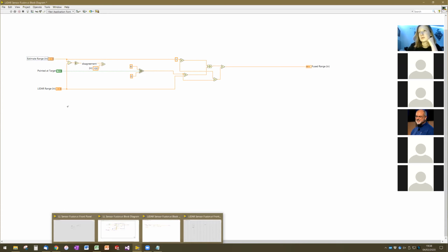On spacecraft, what they typically do is a vote of 2. So there'll be 3 identical sensors for every single sensor on that spacecraft. And if one of them disagrees with the other 2, you go with the 2 and assume the third one's wrong. We typically don't do that because we don't have enough money or the need to have that kind of redundancy, but that's one of the approaches people use: put a lot of identical sensors on and vote between them. Okay, so let's proceed.